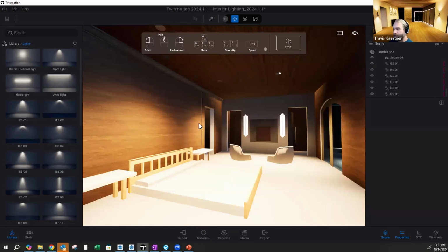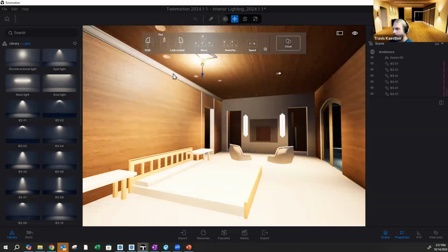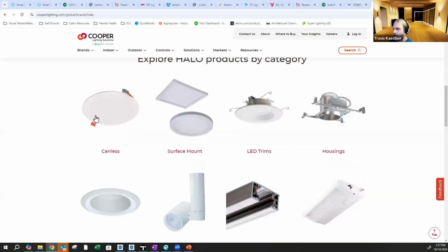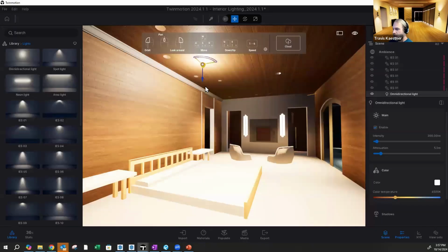But you can actually use that technique. You can fill the space with light by bouncing light off the walls. And it's another way to help eliminate glare instead of just having a big surface mount downlight. A lot of these canless ones like this that don't have the optics are glare bombs, and you only get light within the first 3 to 4 feet. It doesn't get light down to the ground, to the work plane where you're trying to work.